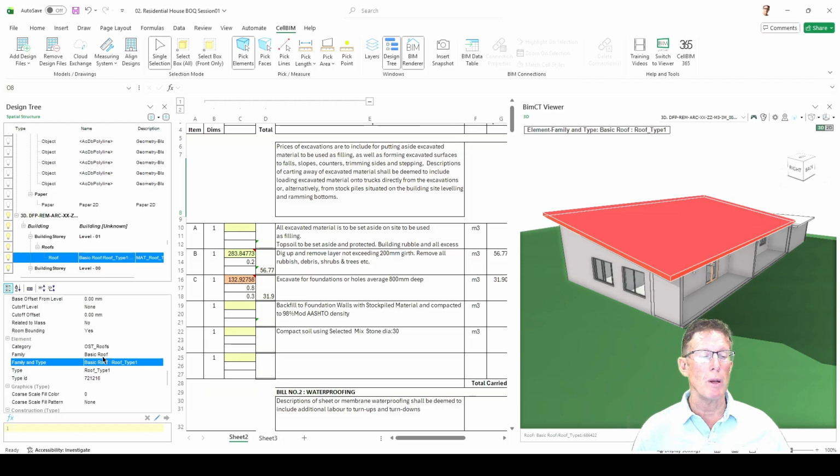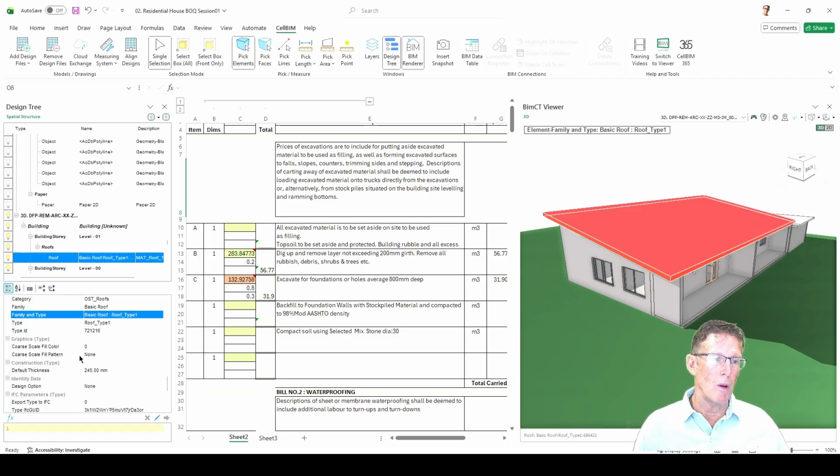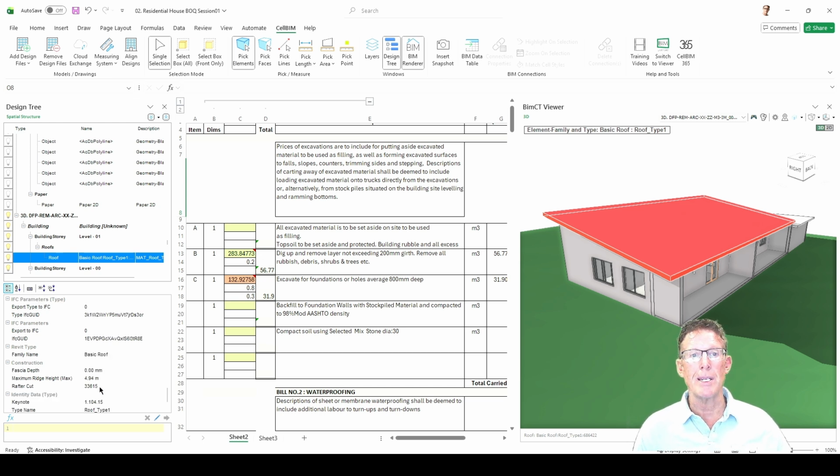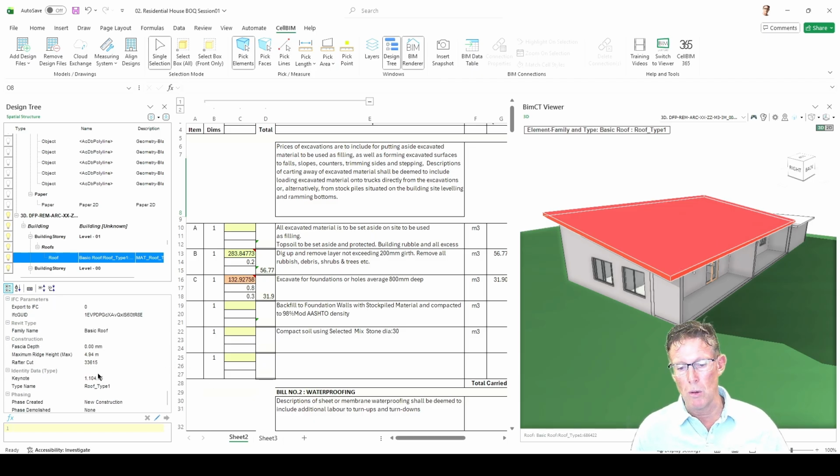We spoke about that when we looked at the 3D model of the pump. Depending on what properties there are, the properties may differ depending on the design. So it's very important to dive deep into understanding how the model properties were given to you, and you just don't assume that the quantities are the same as what the bill of quantities has been given. So check your descriptions against the data, which would be your length, your breadth, your width, your heights. Make sure that they do align with the bill descriptions.